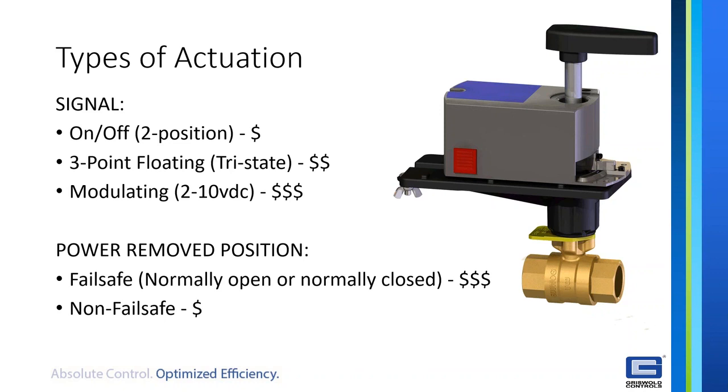In other situations, you want it to fail closed, because you don't need to keep cooling the building unless there's something in there that you need to protect. So it could be either or for cooling. Heating, though, is typically fail open.